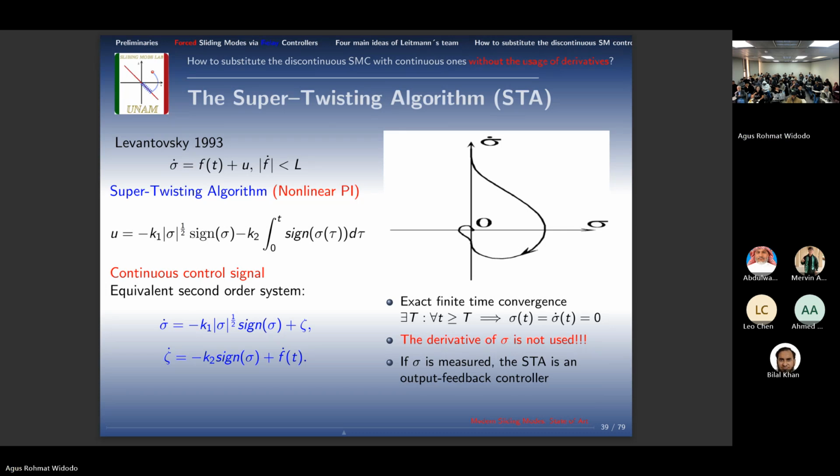Why PI? Because if we do our PI, not the PI you normally see, what happens? Let us prepare a special control, with a special proportional part in the way of sliding mode or homogeneity. So what is it? It is proportional, but proportional to the square root. And here is an integral, but an integral not of x, but of the sign of it. It allows you to do the same job. What is the same job? You can find with this Lipschitz signal, with any perturbations which are Lipschitz. Because this signal is Lipschitz, its derivative is not more than 1.